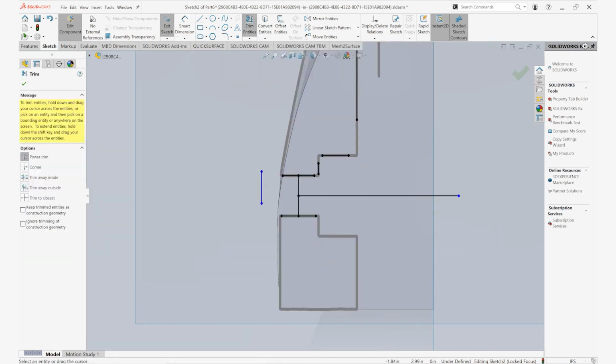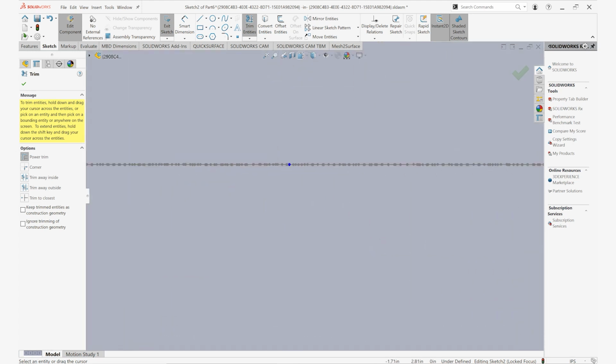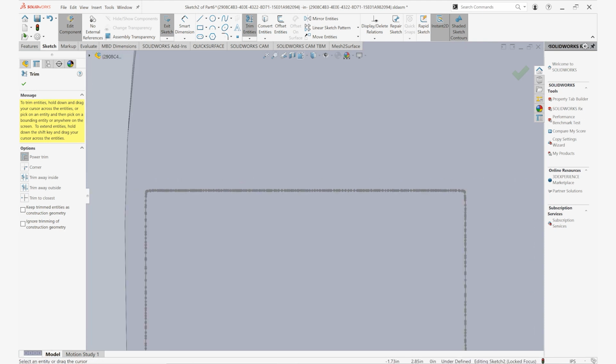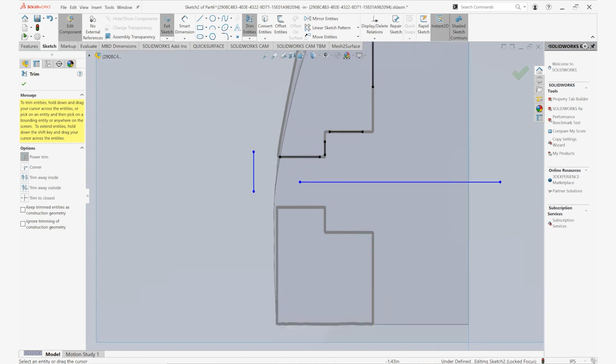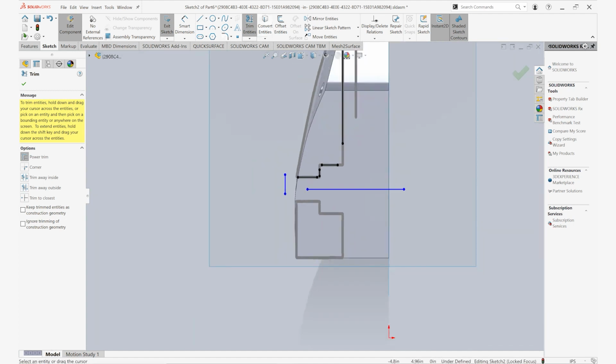This is where our constraints inside of Artec Studio can be really important because it makes it very easy for us to find the center axis of our part and be assured that we are accurately revolving this information around that center point.